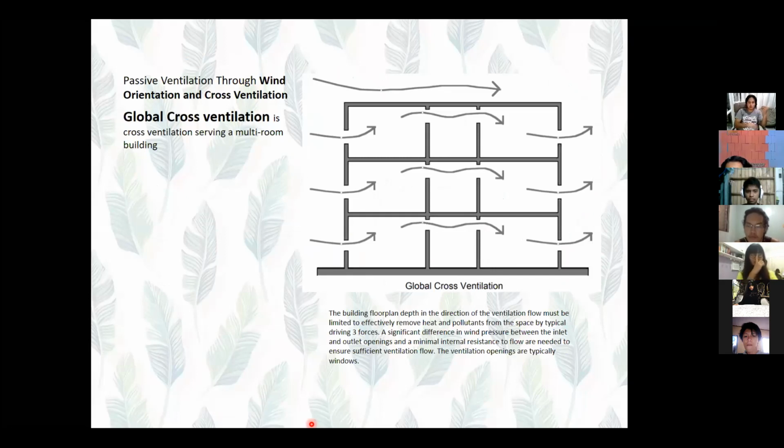So from the inlet, the air goes up, exits, and then slims down again. Even if the air is already hot, we can't maximize the chimney effect here, but at least there's the wind speed. The air is hot, the temperature is hot, plus high humidity. What at least alleviates this is the wind speed, so you maintain and conserve the wind speed. Then when it reaches the bottom, it needs to hit the lower portion of the rooms and it will have evaporative cooling. That's what it conserves.